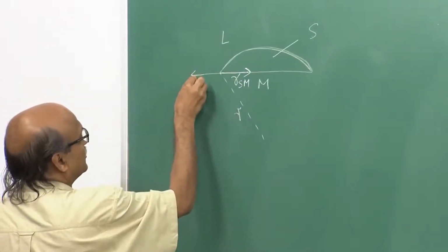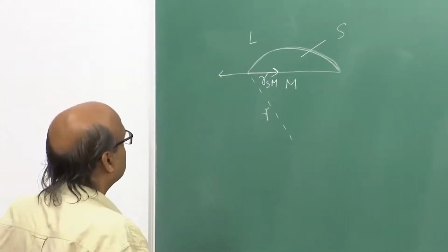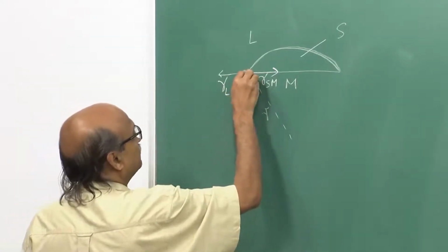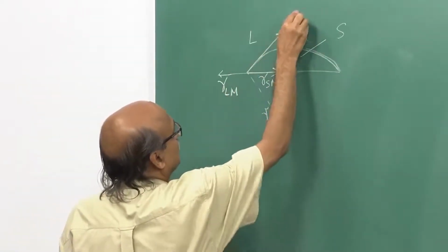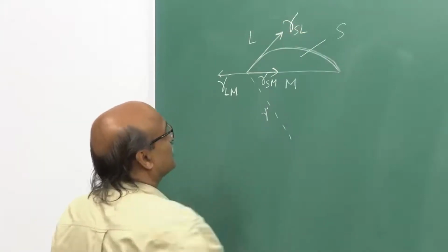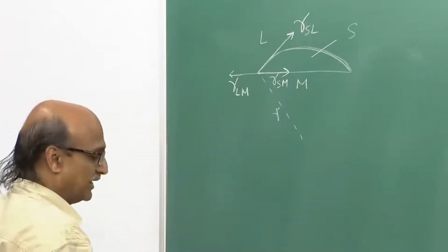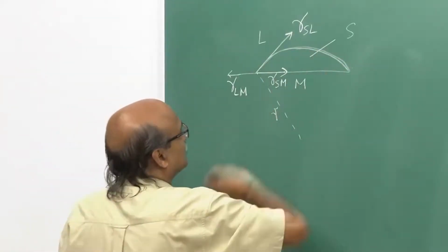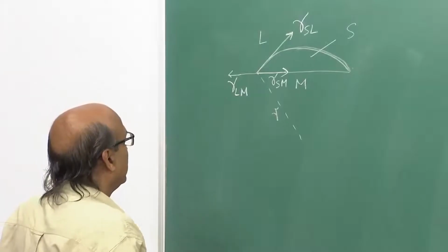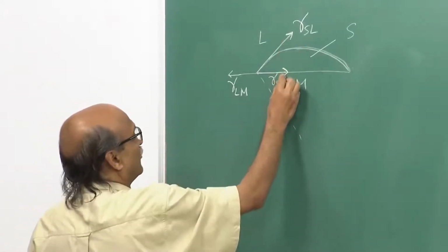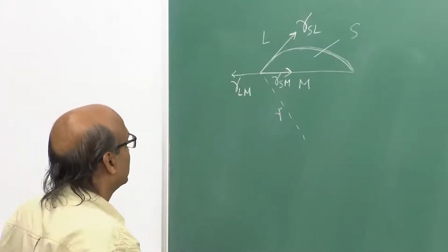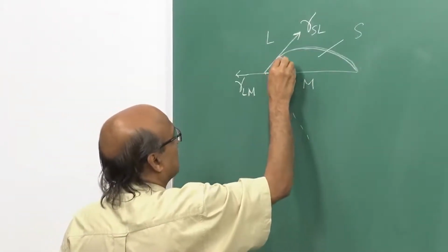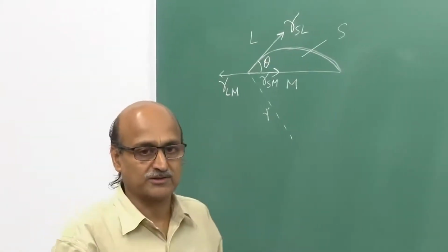There is a surface tension between the liquid and the mold wall, gamma Lm, and then there is of course the interfacial surface energy between the solid liquid interface, gamma Sl. Now, what would be the exact shape of this nucleus would be determined by the balance of all of these surface tensions, and once you balance them, one will find that there is a certain angle theta which is called the contact angle.